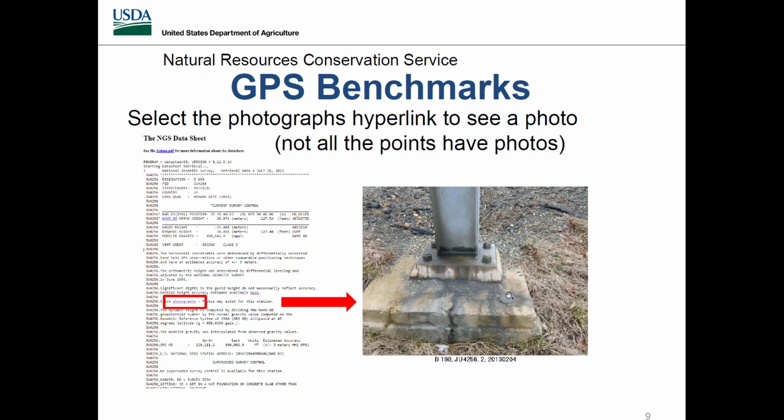If you are close to any GPS point that you brought in from that in Civil 3D, you're able to move your points to that location, or maybe you shot it and then you know exactly where that shot is. You can change the elevations of your survey based off of that actual point elevation.